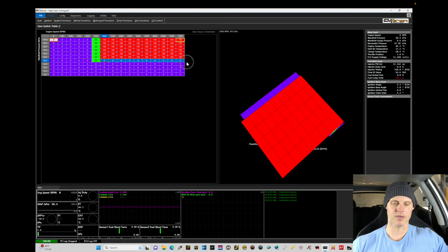This will act kind of as a hysteresis, so it has a way that it can transition between those two areas. It's not going to be abruptly on or off. So it's going to give kind of a blending function there. We're going to lock it in here, doing the setup here, and this will allow us to then jump on solely to our table 2 in the VE table to map it out once we get to 3,000 RPM.